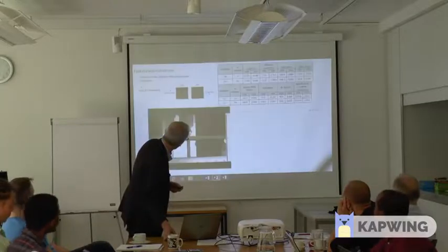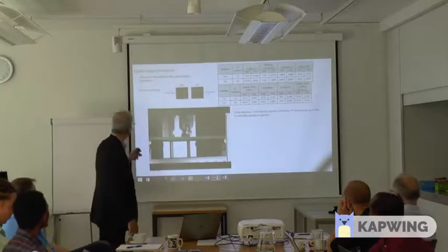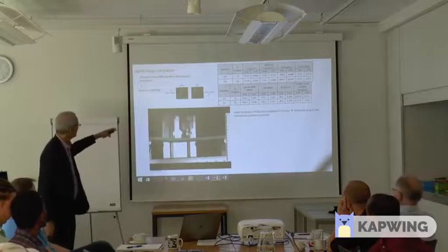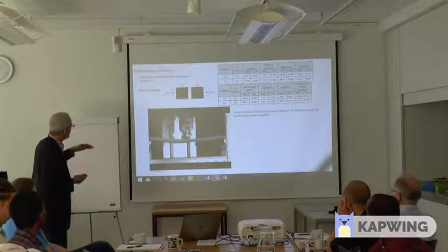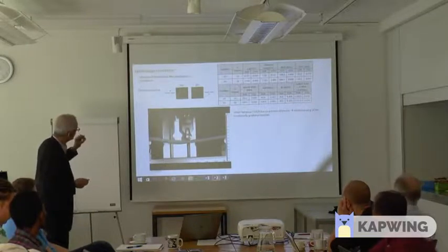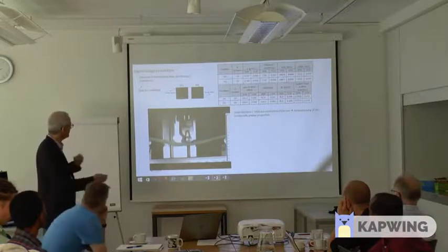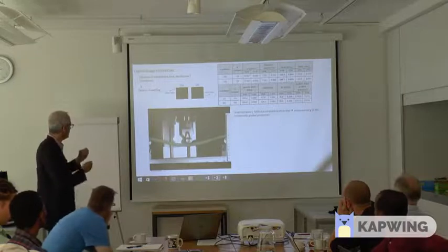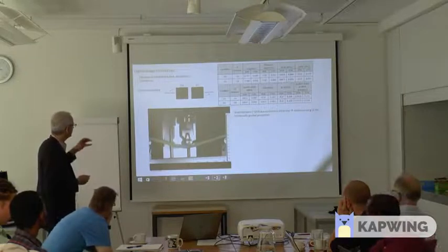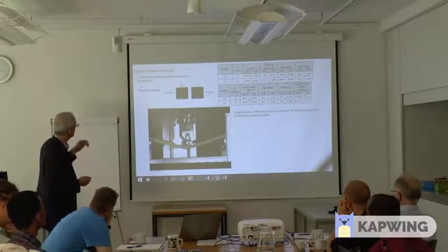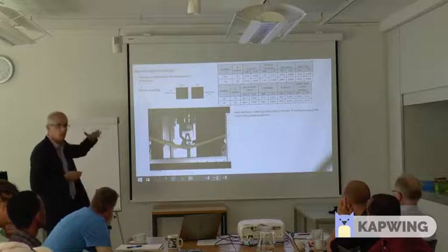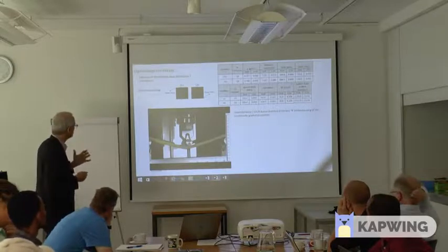If we talk about bending, now it's showing there how it performs, the concentration of tensions, because we are following the displacement and correlating the displacement with the tension. We can see how the material behaves and how the neutral line moves during the bending test.